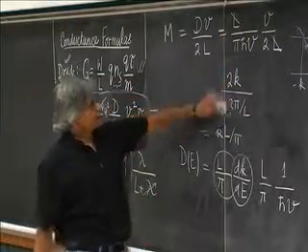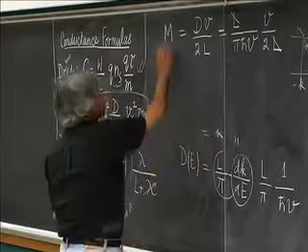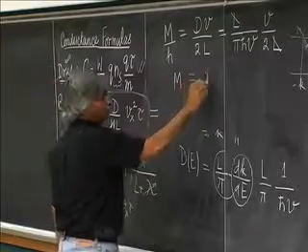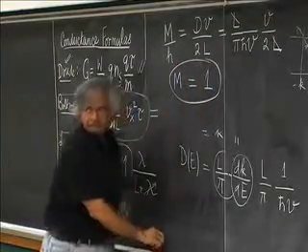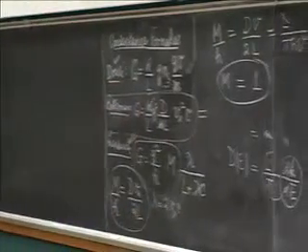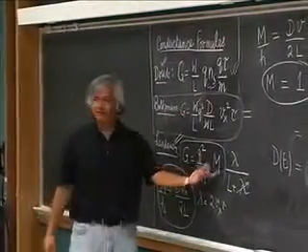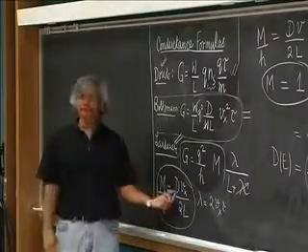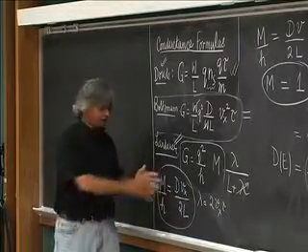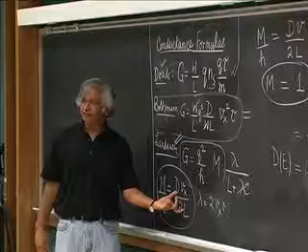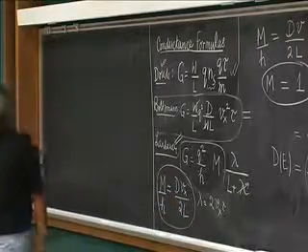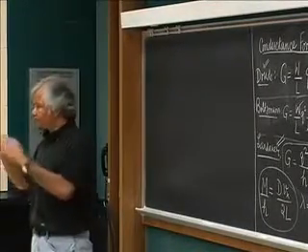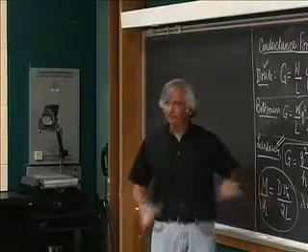So you'll notice the answer you get is, I guess this is M equals h dv over 2L, and so M is equal to 1. So for a 1D conductor, you see, originally I introduced this concept of modes by saying, well, let's take a ballistic conductor, see what current flows through it, and what you get is something like density of states times velocity. And in all of this, of course, there's no h in the thinking. It's all classical as far as we are concerned. We're just talking of some states with some velocity. It could be, as I said, cars on the highway. No h involved, nothing else. We're just taking the states times the velocity.